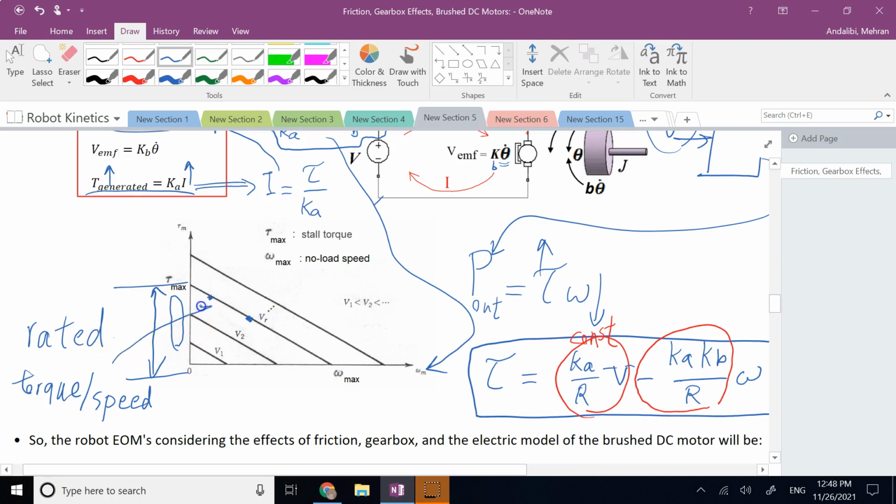This is the point at which the manufacturer thinks you should operate the motor. Now you might say, let's say this point gives me 1,000 RPM, which I do not need. What should I do? Then you definitely need a good gearbox to go with it. If the RPM that you need is 100 RPM and the rated speed of this motor is 1,000 RPM, you need to use a gearbox that has a gear reduction of 10.